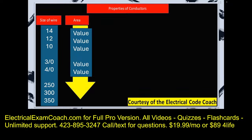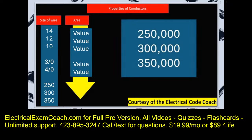So don't worry about if it's solid or stranded. Just go over to the circular mils. Make sure that you're in the area section under circular mils, and you'll find your value. You'll notice when you get down to 4/0 that the values stop. And the reason is because the left-hand side of this table, the 250, 300, and 350, are already showing you what the circular mils are in kcmil. So we have 250,000, 300,000, 350,000. So once you get past 4/0, you're going to get into 250, 300, 350, and all you have to do is add on the 3 zeros.